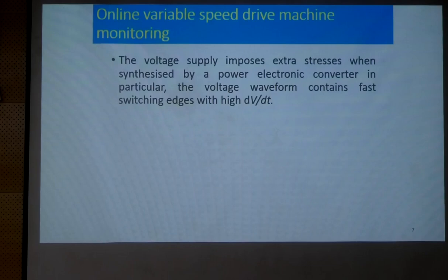So these are all not completely bridging the insulation to ground, but partially it will be bridging the insulation. So once these discharges are incepted for a particular voltage, even if it is minor, gradually with respect to time the insulation will get deteriorated. Thereby it will ultimately cause the breakdown of the insulation.